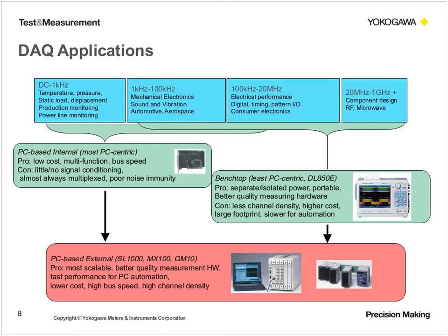So the advantage to using this type of data acquisition device is that you usually will have pretty high bus speeds and high data transfer rates. It's good for when you want to deal with massive amounts of data and when you're working with thousands of channels, and it can be a little bit difficult to manage all that data maybe on a standalone unit. So this is where you would use the PC-based type data acquisition system. On the flip side, this type of data acquisition system is also the most sensitive to noise, as we'll discover later on throughout the course of this presentation.